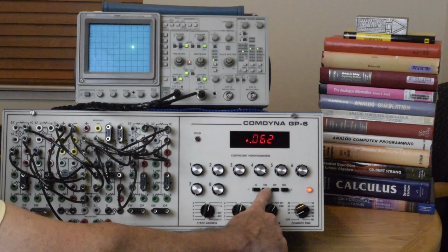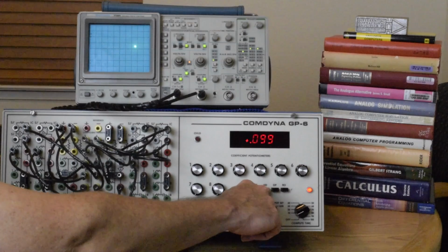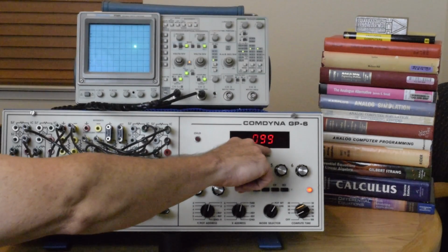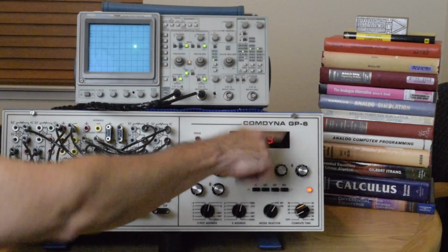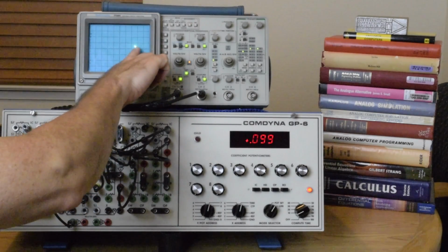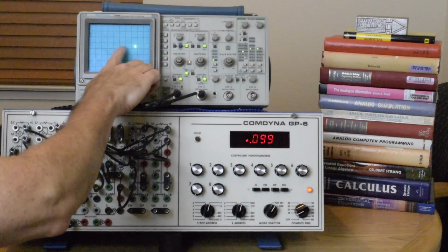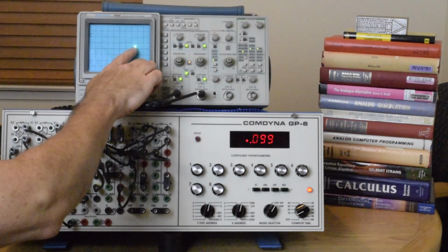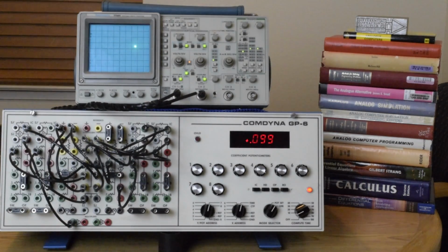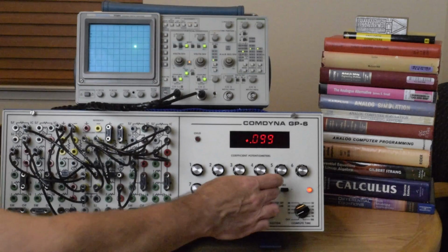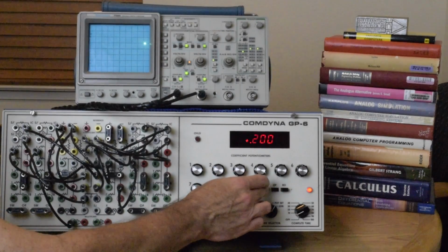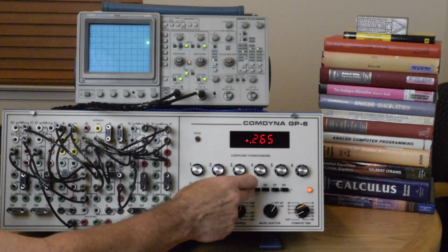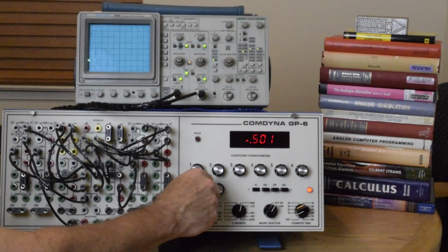And you could actually use this hold mode to stop the problem at any time. And then you get an actual value of the output of the analog computer at that instant in time. You could record that off of the oscilloscope by measuring the time across the x-axis and the vertical displacement in the y-axis, and then calculating that against the range. Then we can continue the operation until we're finished, and if we wanted to do another run, we could go back to the initial conditions.